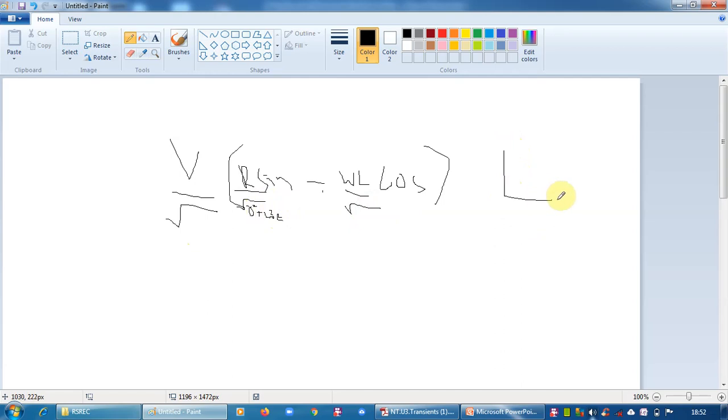Now from the previous impedance triangle, this is R, this is XL, this is Z, and this is the impedance angle theta. Now this term, R by root of R square plus omega square L square, root of R square plus omega square L square means this Z. So R by Z, how can it be written? This is nothing but cos theta. Cos theta equals R by this magnitude Z, where Z equals root of R square plus XL square. So for this we can replace R.